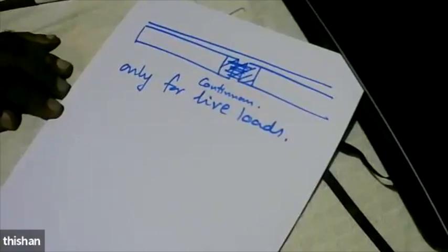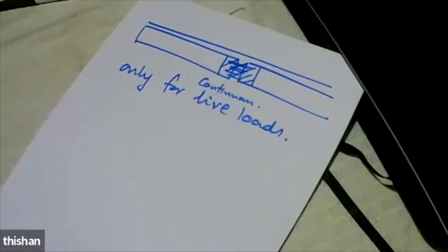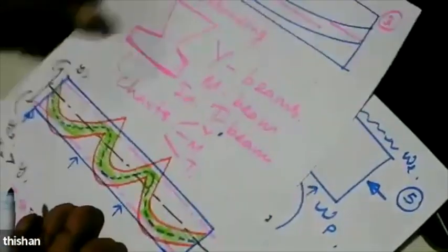Because designing a continuous prestressed concrete beam is nearly impossible. You do a set of calculations, spend a lot of time, find a cable profile, find a prestressed force that is going to work throughout the length of the beam, and then you find the cable within the cable profile zone, and basically this is a zone.